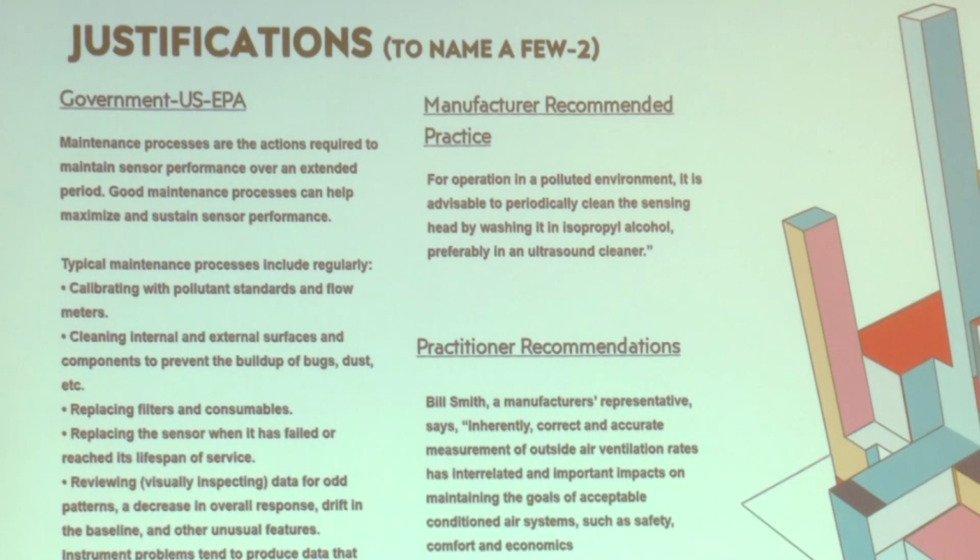What engineers and practitioners tell me is, well, we really don't need filters on the outdoor air because we expect the maintenance and operation personnel to clean those airflow monitors every 6 months or a year. Guess what? It doesn't happen. They don't clean them, and they don't work. Once they let it go, and once they're bad, they don't get any better. And when you try to clean something when it's really, really dirty, it's gone. It's never going to come back to what it was.